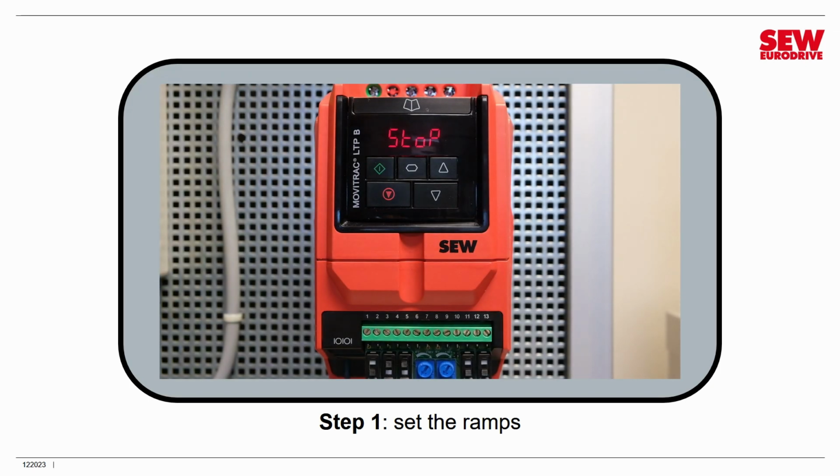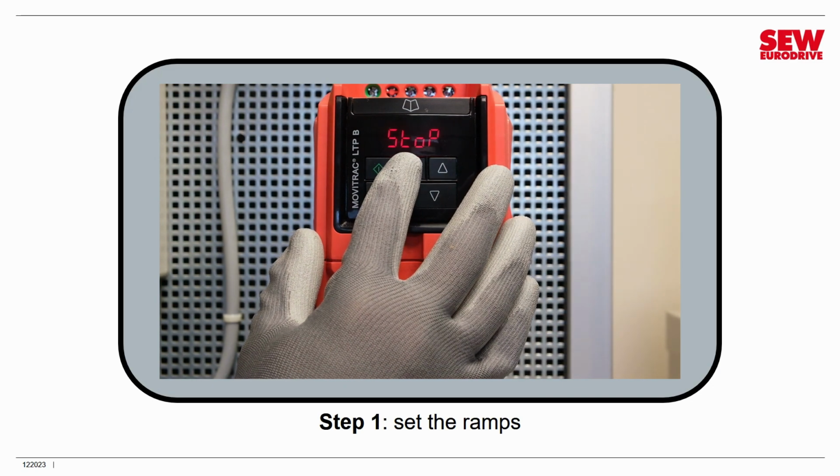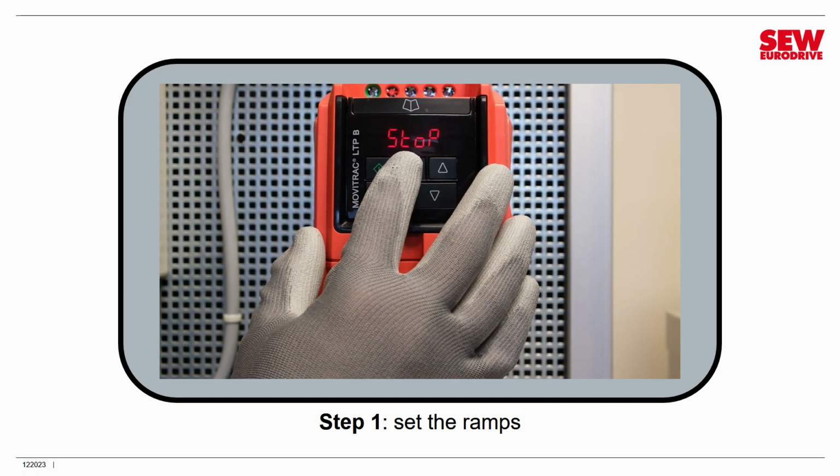So the first thing I'm going to do is disable my VFD. It's always smart to do this before you edit parameters, so I'll turn digital input 1 off. I don't have to put it into controller inhibit mode, I just should disable it. Now I enter parameter edit mode by holding down the navigate button for a few seconds.